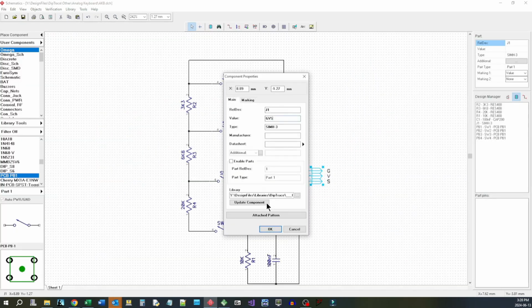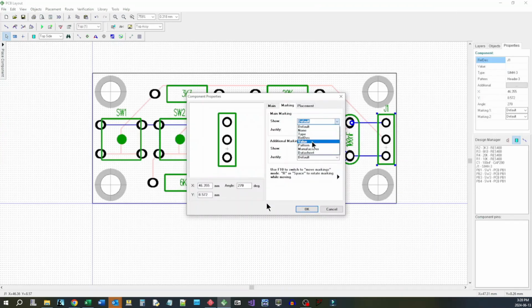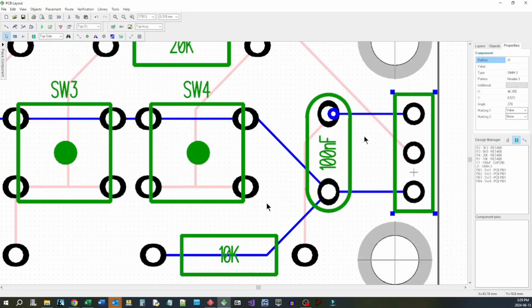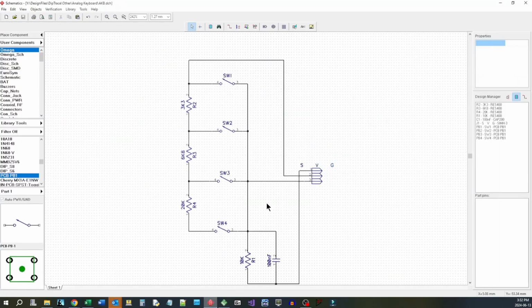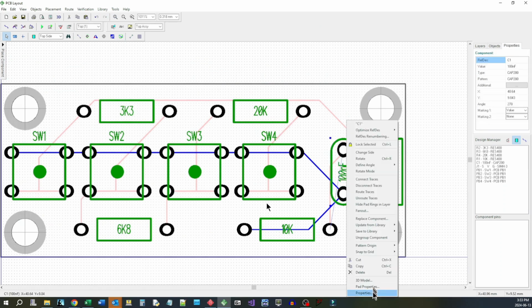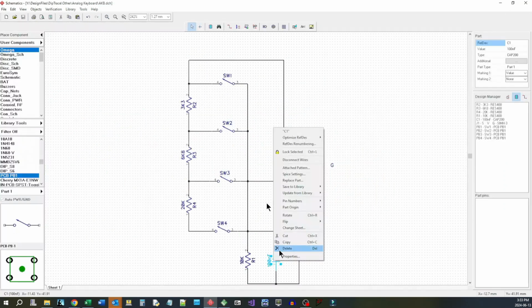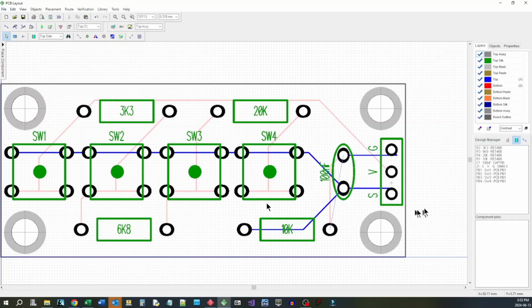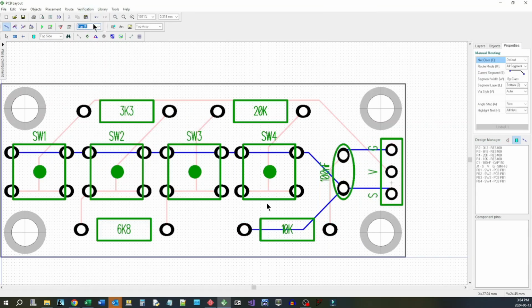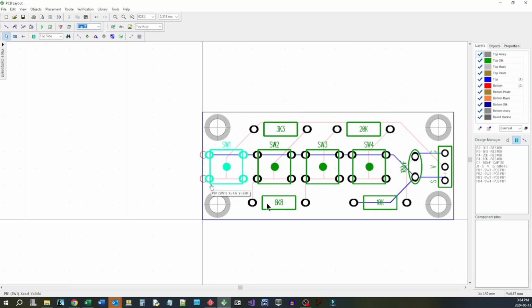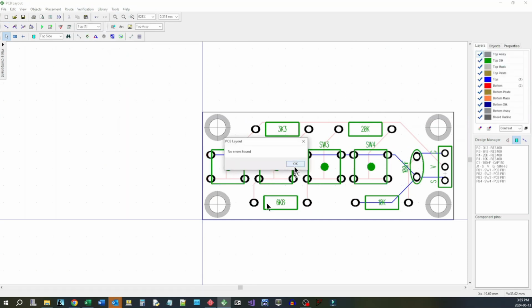But now we're going to go in and change that label for the SVG and how it appears here on the PC board. So we'll give it a first try. It's too close together. We're going to go out and spread it out in the schematic. Then we get it on the right side here, and we have to change that one capacitor there because I got the footprint wrong on that one. So there we go. Now any errors that came from the changes that we made, we correct for all those.